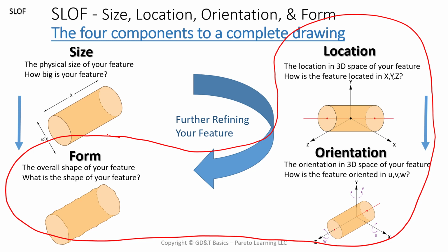If they only controlled location and orientation, that would be position, right? That's the position symbol. If we have datums A, B, C, we're not only controlling the locations from maybe the sides of our part, but we're also controlling the perpendicularity to the face of the part, or whatever we're using as the perpendicular datum. So position controls location and orientation. It's that go-to symbol. Now, runout is bringing in form into this.